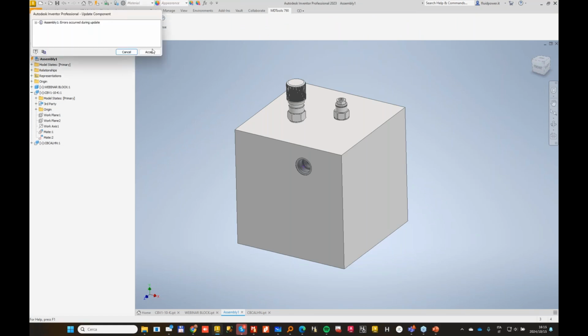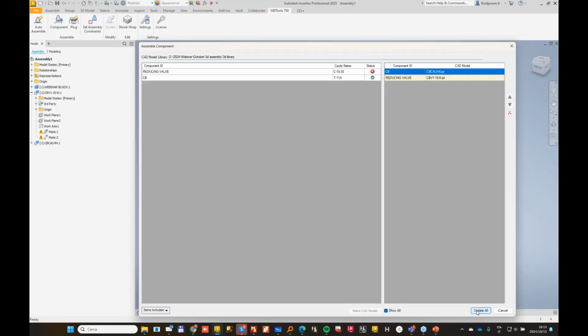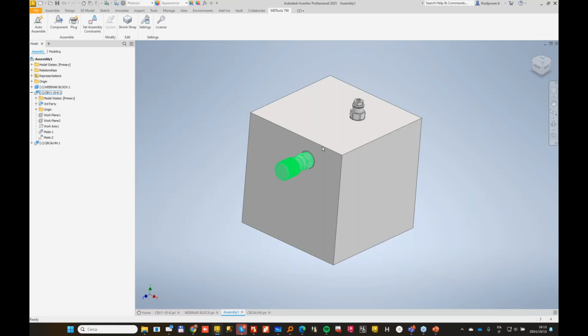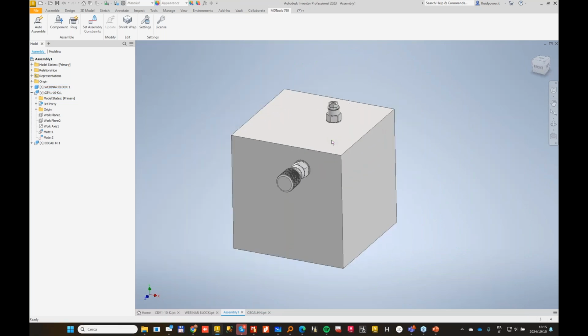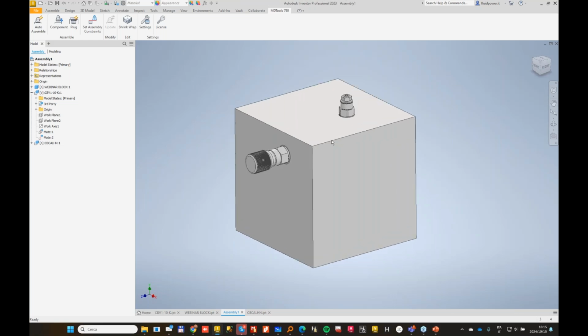If you do update, there are errors or build errors, which we can fix just by doing a component update all. Since we have tied a component to the cavity, now MDTools is able to rebuild and recreate constraints. We will use this technique in the next MDTools webinar regarding a small design exercise.